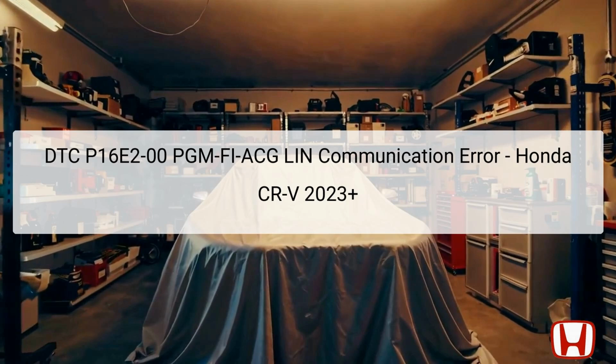The diagnostic trouble code, DTC P16E2-00, refers to a communication error between the Powertrain Control Module, or PCM, and the alternator via the Local Interconnect Network, LIN communication system. The alternator's primary role is to generate electrical power for the vehicle's systems while the engine is running, and it also charges the battery.